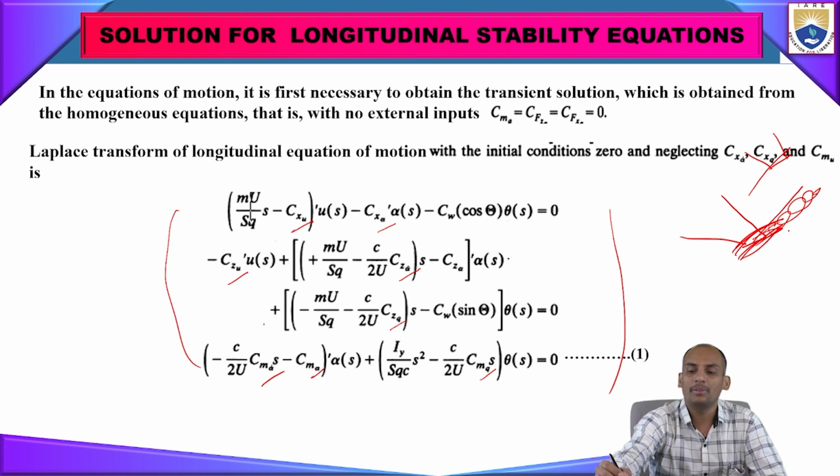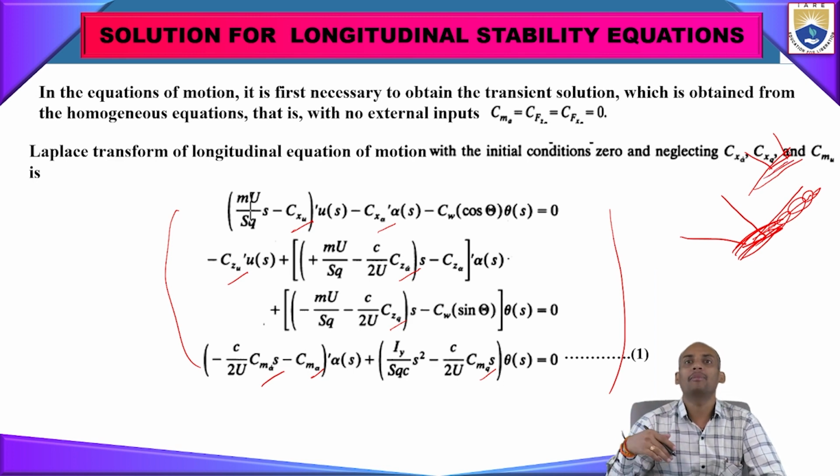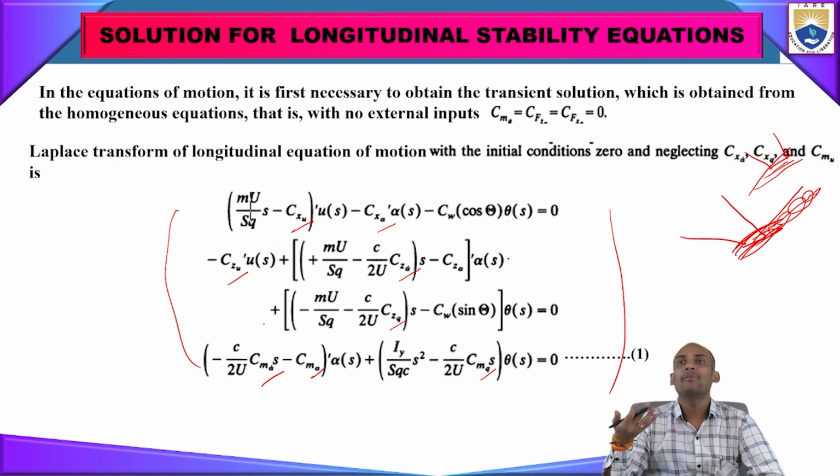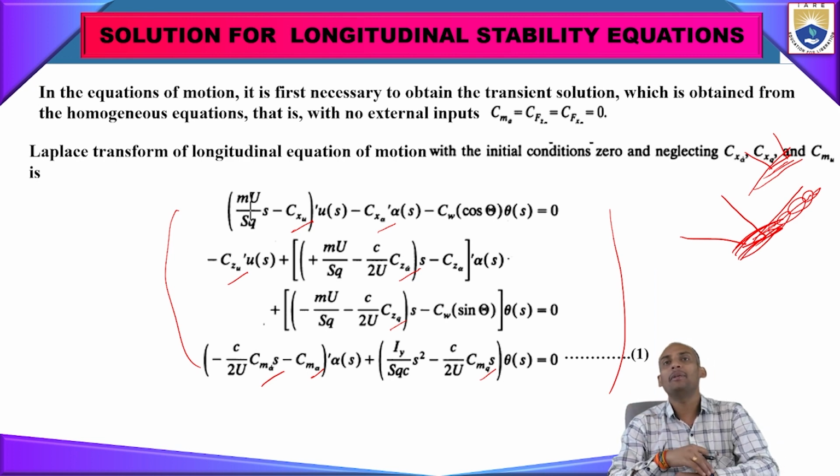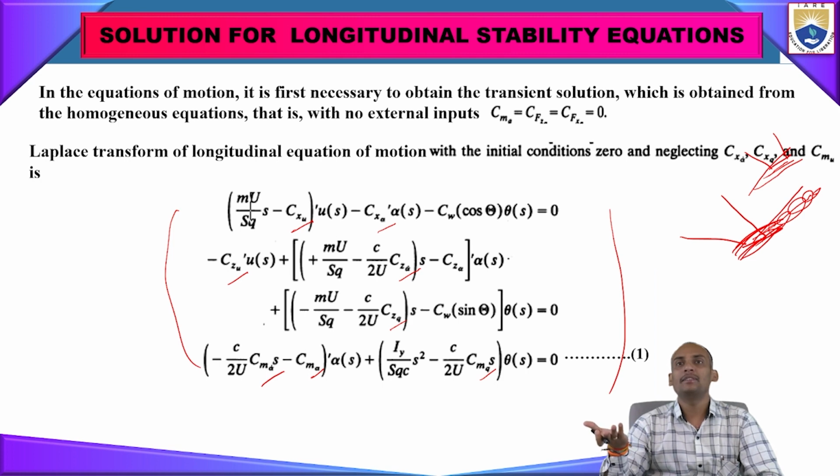If the vortices are formed, they will continue up to the tail also. There the downward velocities will be adversely high. Whenever the velocity is high, the pressure will be low. If the downward pressure is low, there will be an adverse change in lift also. If you give the elevator deflection, there will also be changes in lift. If these conditions happen,